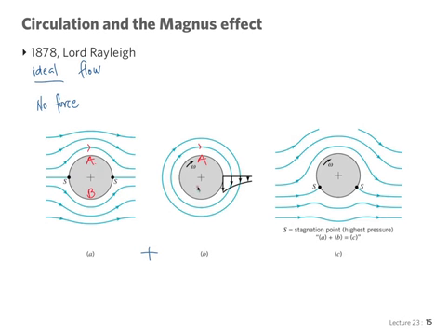In point B, we have the parallel flow going from left to right and the circulatory motion going in the opposite direction, and so there's a reduced velocity in point B. So this is the combined effect. In point A, we have a greater velocity, and in point B, we have a reduced velocity compared to just parallel motion. This is still ideal flow, okay? Now, this result was used to explain the so-called Magnus effect.